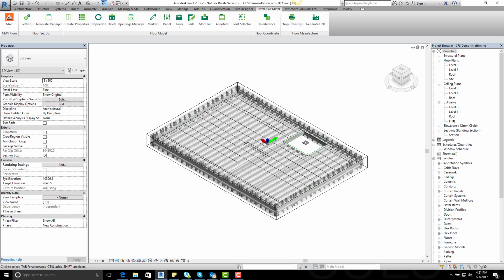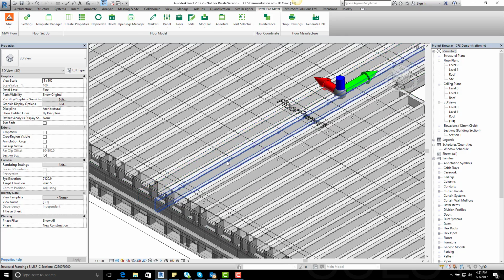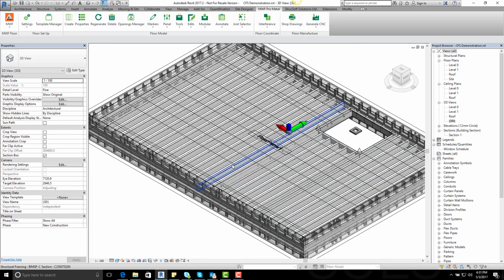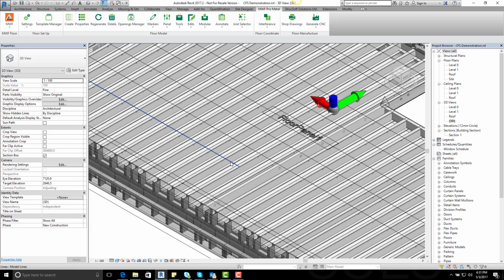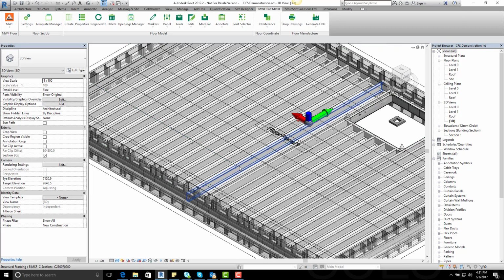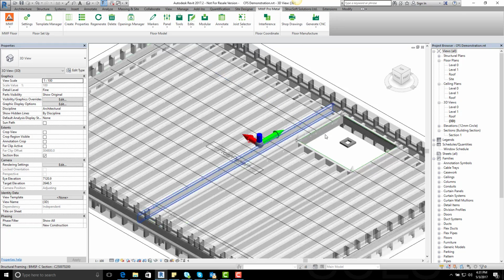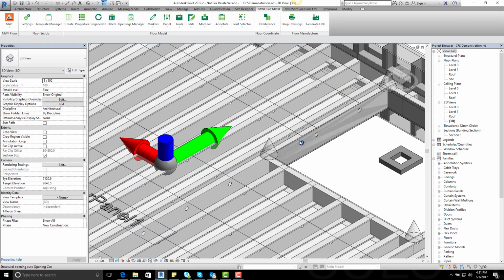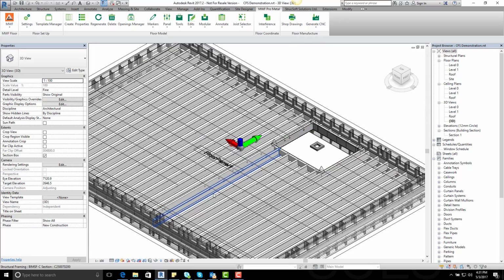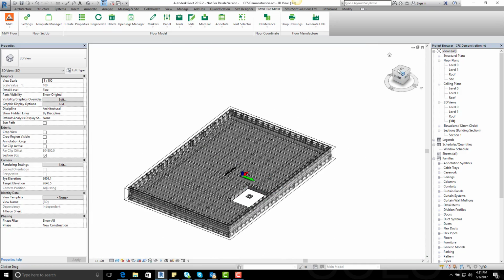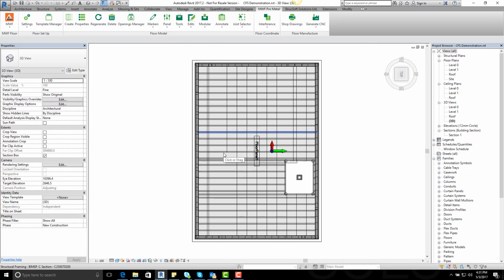If we have a look, you can see here that half of my holes have now been applied and half of it has not been applied, because of what I told the marker lines, because I put the marker lines up above. And as you can see, because I shifted this marker line near to that, it is now applied there. And same, if we look on the other side, it has done the same thing. And that is how you produce a hole series using our floor module.